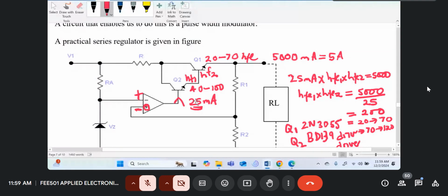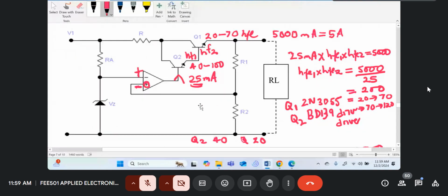So that is the best way to design an output stage or the control element of the series power supply. Now, most of our lab power supplies are actually obtained from this. They use this exact circuit, and then on switching ones onto the heavy transformers. So we have two of them, one from 0 to maybe a positive value, maybe 30 volts. And then we use an opposite design, using PNPs at the bottom. So we got 0 to maybe plus 30, 0 to minus 30.